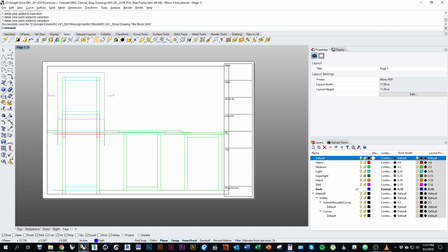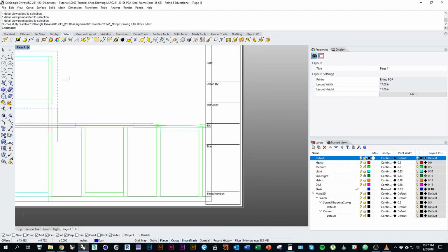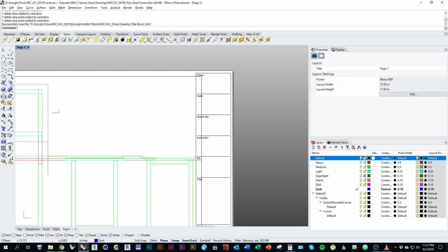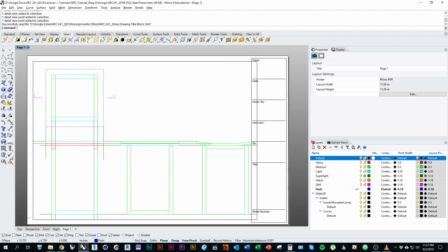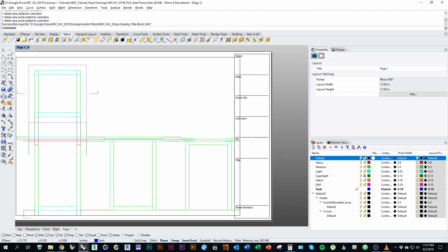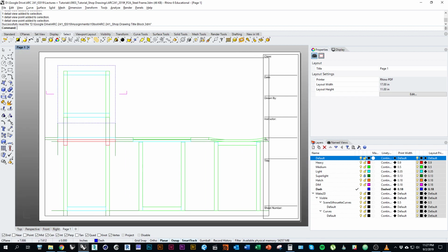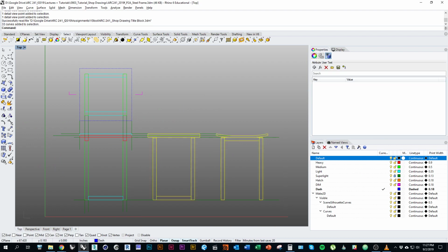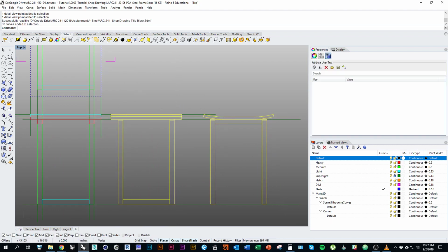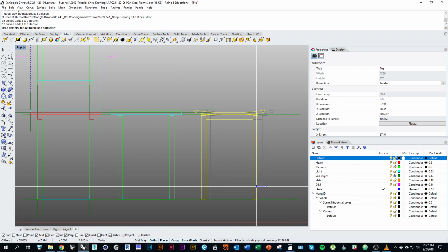Now, first of all, the title block is basically a standardized section where we state all the information for what the drawing is, how many pages there are, where we are in the document, who drew it, all that stuff. So on each page, we want to avoid overlapping with the title block on our layout. So I could go back into model space and just tighten up my layout a little bit in order to use less space.